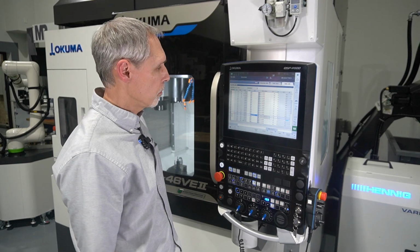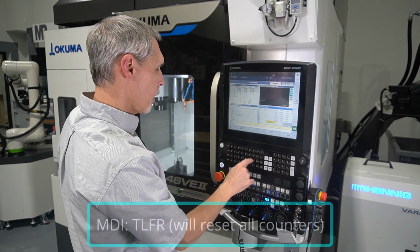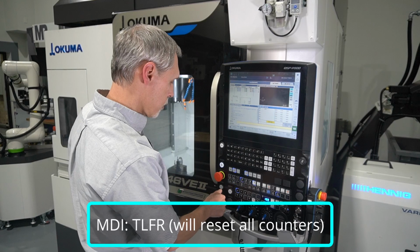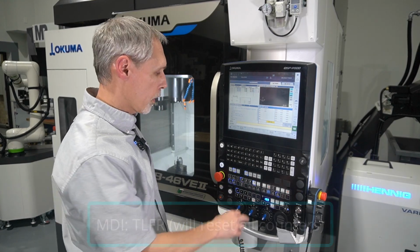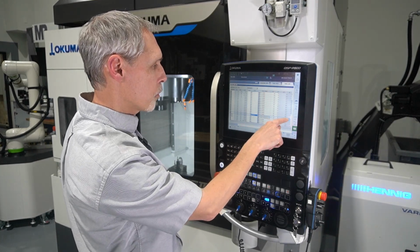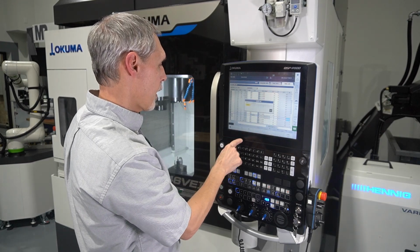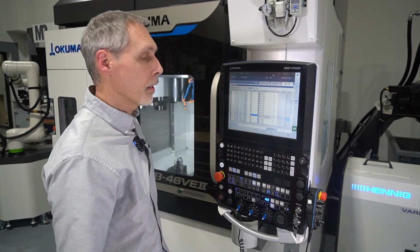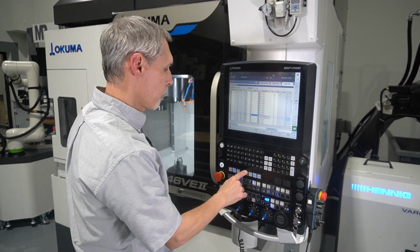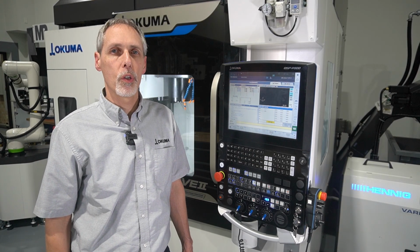A quick way to do that is in MDI. We come in here and we do TLFR. Is a quick command to reset the tool life on all the expired tools. Cycle start. Now if I go look at my tool data page, I can see that my numbers are all set back to 0. I still need to set the flag back, so I can set that to OK. And now I'm good to go. I can start production again. So that's a quick primer on how to use the Tool Life Management function on the Okuma OSP control.